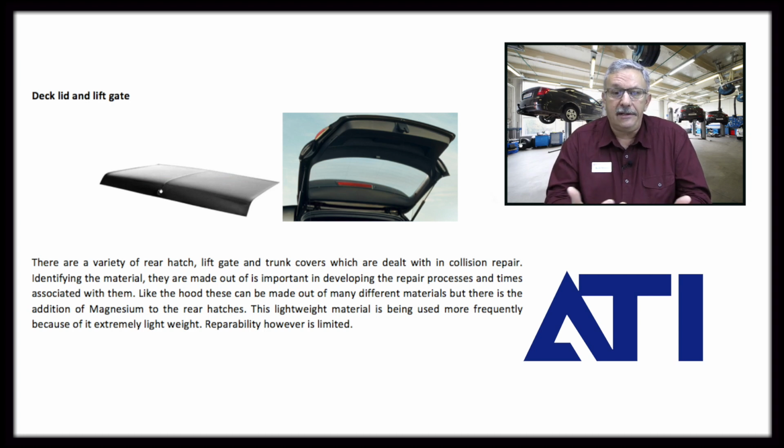We go into All Data, let's say, we research the information for that part that we're going to fix, and I kind of use this as a rule of thumb that works real well. Anytime I'm going to heat a panel, for whatever reason, whether it's welding, cutting, whatever the case might be, I want to pull the data for that part specifically so I know what the repair parameters are. That will be the thing I want to do as a repair planner is I want to make sure that I'm providing the repair information that's required for that part to the technician.